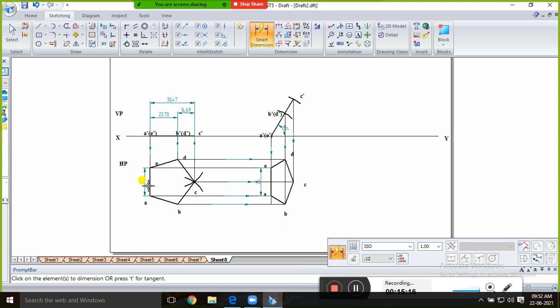But if you consider a perpendicular bisector or any other edges like ED or DE or BC, these edges change. In the first position it is somewhat 25 and in the second position it is less than 25. If the inclination is with respect to these edges, then you have to go with the locus method. But in this problem, and most problems, they give the same resting edge inclined. The same resting edge is inclined.